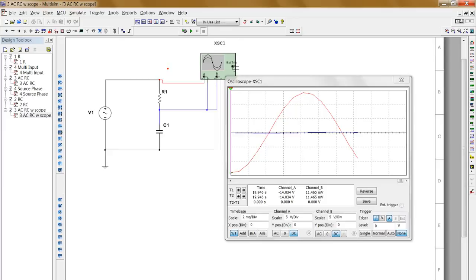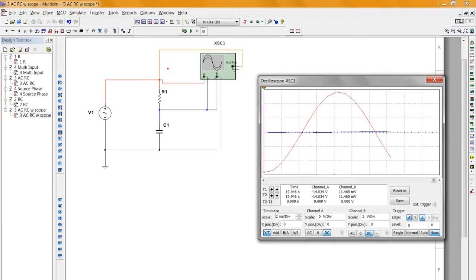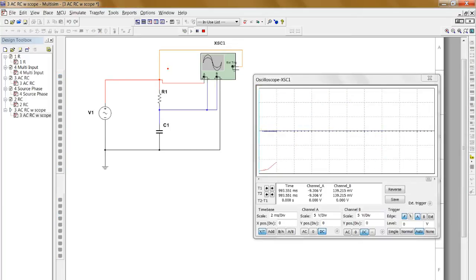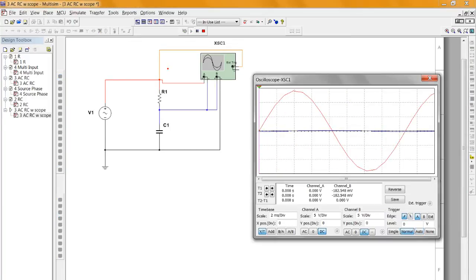So the trigger is not on. I must have opened the wrong one of these things. So I'm putting my trigger on the waveform coming out of this sine wave generator, and I'll put my trigger on automatic, and hopefully that should work. So let's try to run this again. No. What if I do normal? There we go. It's normal triggering. Okay, so I'm triggering fine. It's a little jagged, I can adjust that a little bit, but I'm not going to worry about it.